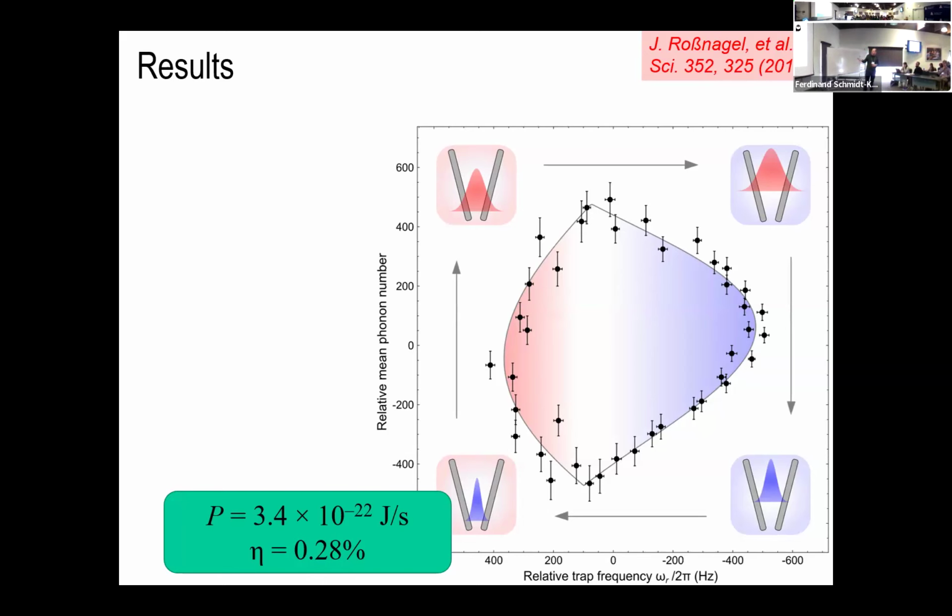So you see, this doesn't resemble too much our original Otto cycle. It's what Ronnie said, it is in principle these 4 steps, but they are all kind of mixed into each other. And we try to get this area. In reality, it would be a much larger rectangle, and we just get a leftover of a little bit of this, so to say, because all the corners are taken away. Yeah, and that reduces the efficiency also a lot. Because the steps are merging into each other.